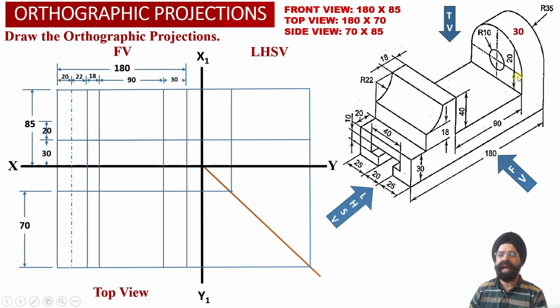Now we also know that onto the right hand side element number 3, which is a vertical web perpendicular to the front face of the solid, the center point of this circular slot and the center point corresponding to this semicircular top portion of this vertical web, it is going to lie 20 millimeter above the top surface of the horizontal web over here.